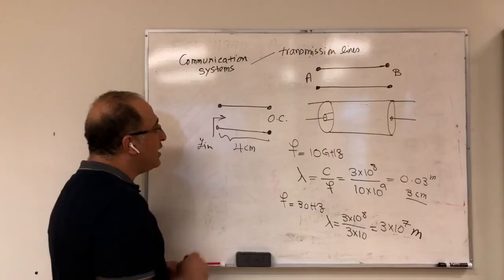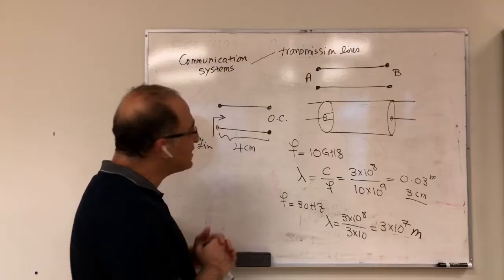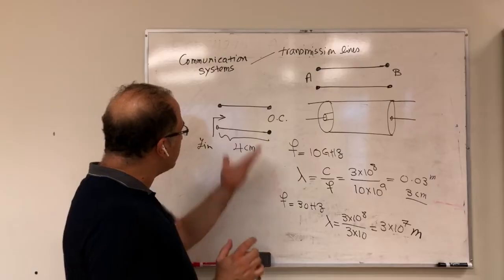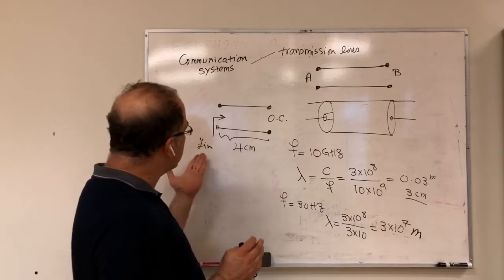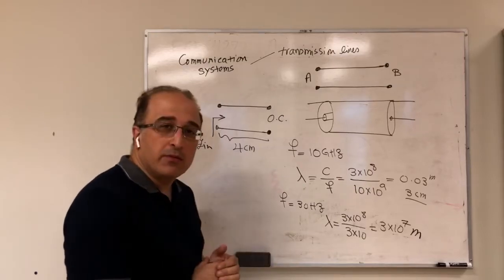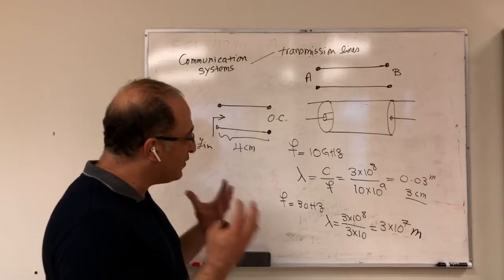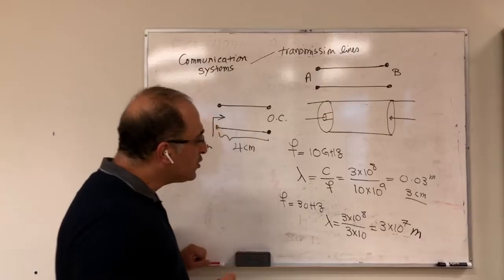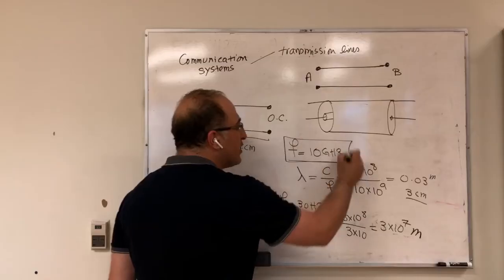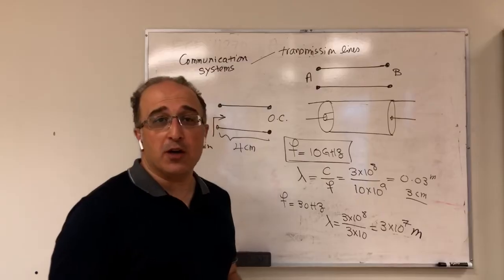In this case, you have to calculate that, and you're familiar with these from your previous courses, but still, I'm going to go over it when the time is right. Just to let you know that, again, at 30 hertz, this is exactly open circuit. When you go to 10 gigahertz, not anymore. So that's something that you should keep in mind. This is the definition of transmission line. And remember that in antennas, usually we are dealing with higher frequencies, like 10 gigahertz. So that's why transmission lines become very relevant when we talk about antennas.